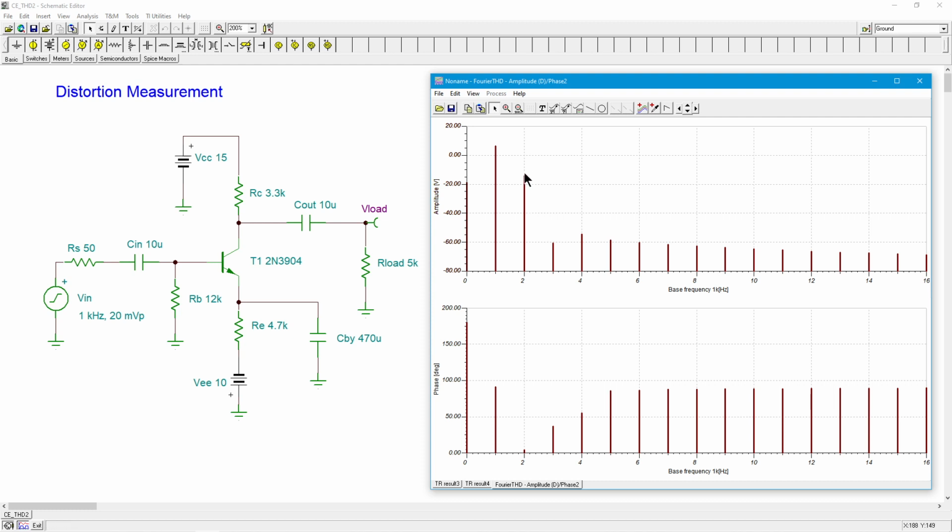That doesn't mean the distortion is the same, because the first amplifier could have, like this, a very strong harmonic here at 2 kilohertz, pretty strong one at 4, and all these other ones are pretty weak. The other amplifier, which is also coming up with the same total harmonic distortion, could have nothing here at 2 kilohertz and a huge value at 3 kilohertz and maybe 5 kilohertz. But when you add up all these extra pieces, it's going to add up to the same total percentage, right? So THD is kind of a gross measurement in terms of the distortion of the amplifier. It would not be true that if I had two amplifiers that both measured the same, like in this case, nearly 10% THD, they're going to sound the same, because the distribution of these harmonics could very well be different.